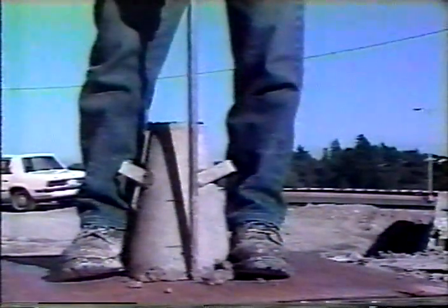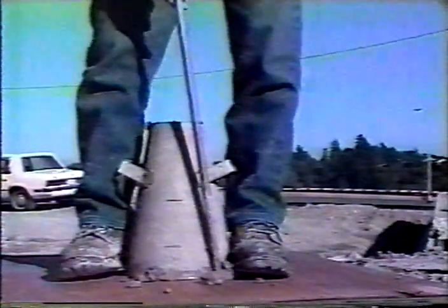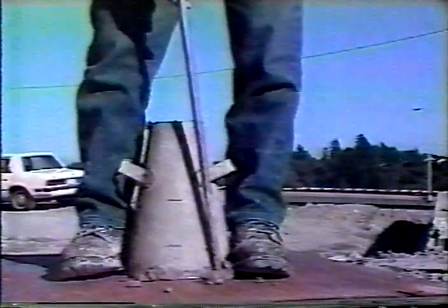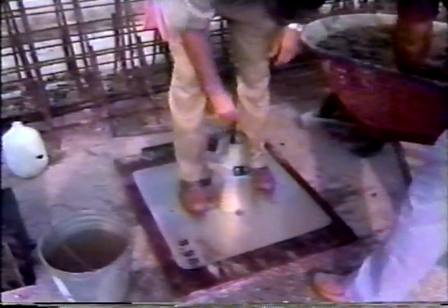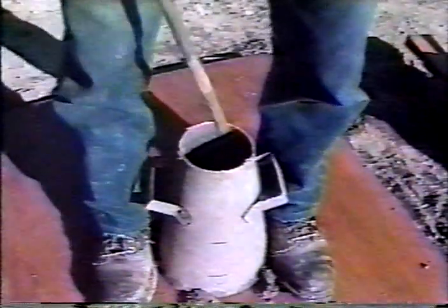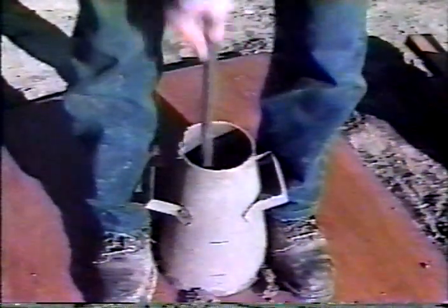Starting at the perimeter, with its rounded tip downward, the rod is inclined slightly to match the slope of the cone. Otherwise, the concrete closest to the cone's sides will not be properly consolidated. The rodding should go to the bottom of this first layer, but just tap the base. Each layer is rodded 25 times, with about half of the strokes made near the perimeter. A spiraling pattern should be followed as the rod moves toward the center of the cone. The strokes are distributed uniformly. As the rod is moved away from the perimeter, it's returned to the vertical.